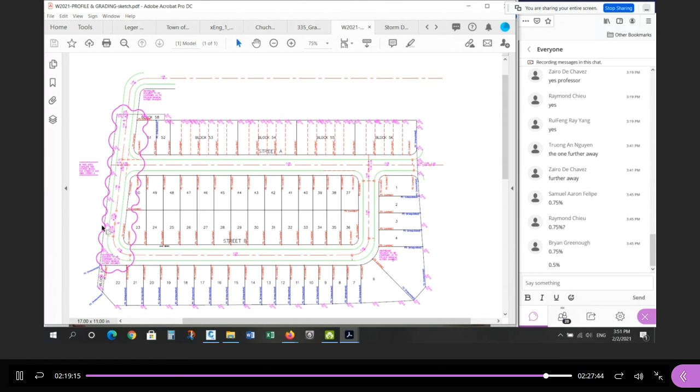All right. Any questions so far? There's a little bit of give and take. You don't design a road and walk away and design the next road and walk away. You might do a little bit of both. I designed street A up to here, and then now I'm going to design street B all the way up to here, and I've stopped. Now I need to design between this point and this point, keeping in mind the concept: from here to here, we're going to have a high point, a high point, and a low point in between at this location. That's the concept here, and I'll go through more details. Any questions so far?